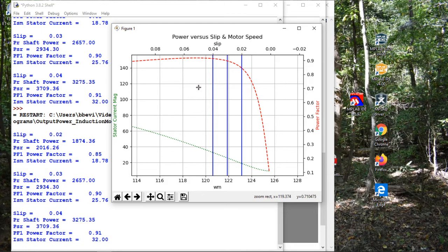Low power factors are bad because that means you have really large currents, and most of it's reactive power, but it doesn't matter as far as the power company is concerned. That's bad. They need bigger cables and stuff to carry that heavier current. So it looks like 0.2 to 0.4, 0.4 may be even good, or 0.3 gives you a higher power factor.